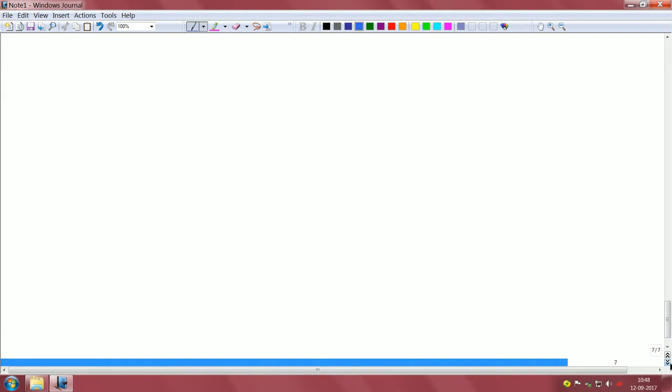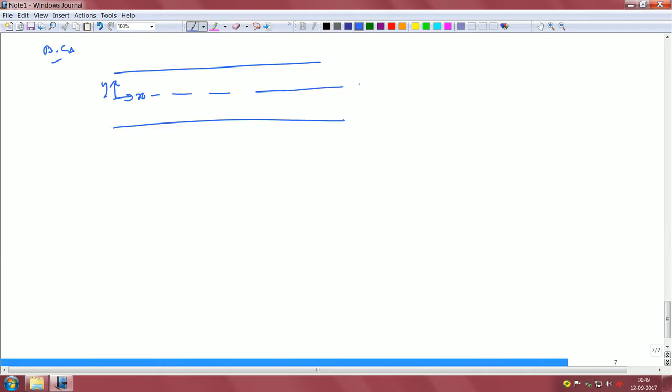Now that we have this particular equation, we do not need boundary layers anymore. I mean, we do not need scaling arguments anymore. We can simply solve the equation from first principles, right. So, we can write the boundary conditions first. As we write the boundary conditions, let us take this as x, this as y, this being the axis. You can have it in any other way that you want, it does not matter. So, u is equal to 0 at y equal to plus minus d by 2. The simple reason is that these are walls, so the no-slip condition applies.